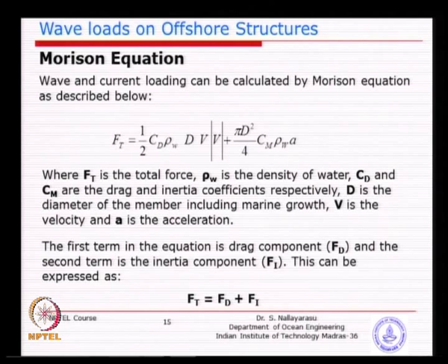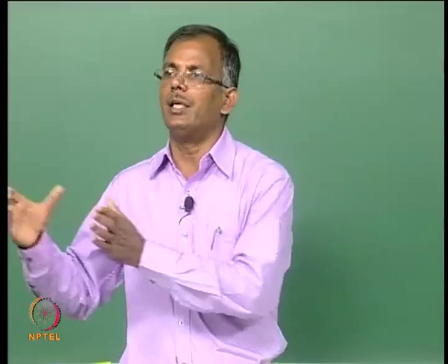So, we call it the added mass coefficient, 1 plus Ca, and that Ca will be calculated depending on the geometry. For example, if you have a circular cylinder moving in fluid versus a square cylinder, you will see that the volume moving together will be different.